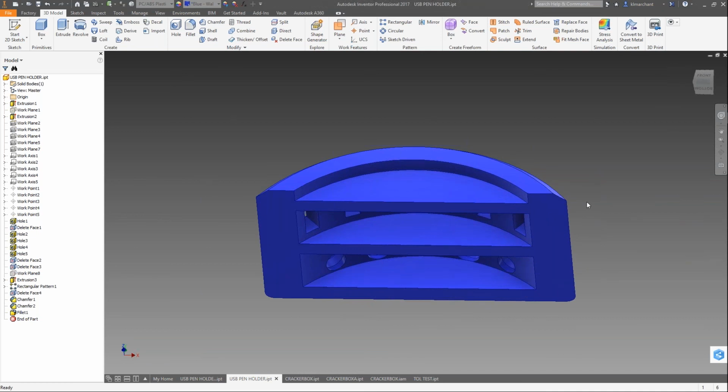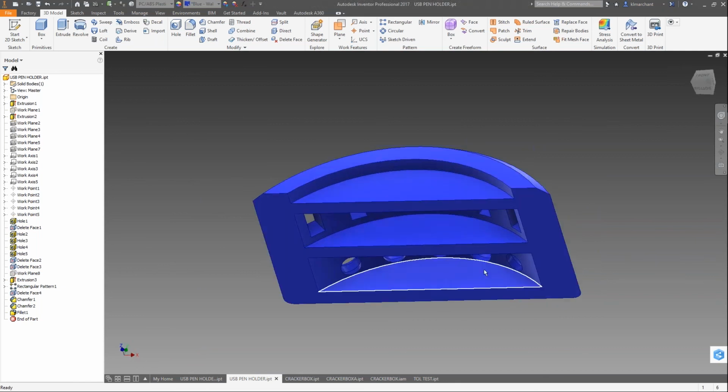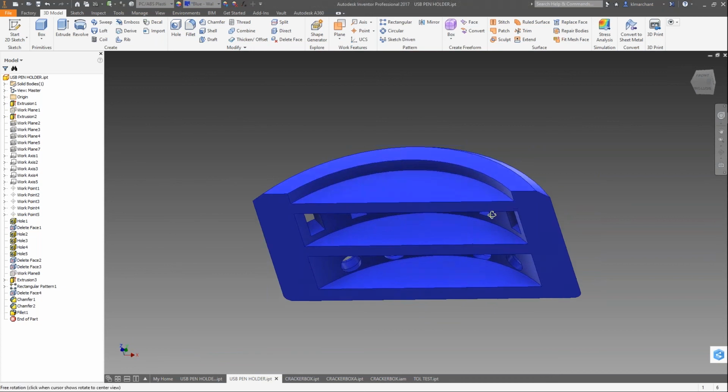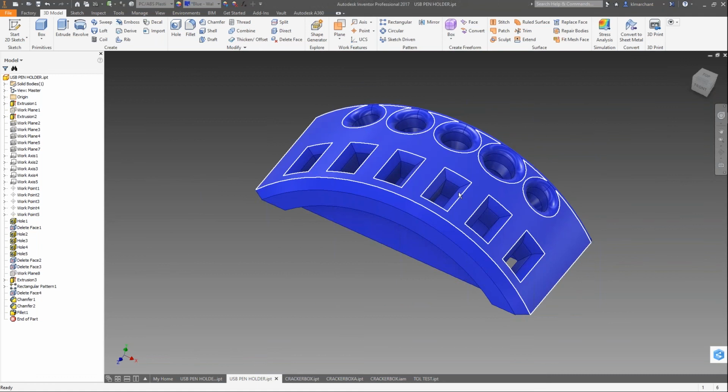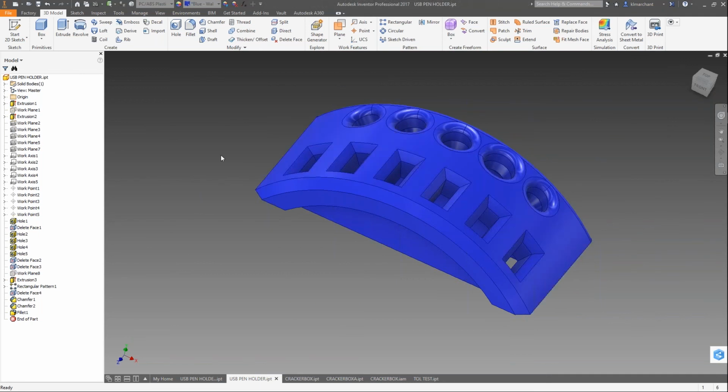That was beneficial because this printer's support material wasn't always the easiest to remove, and that's something we want to pay attention to with FDM or FFF technology. If we don't have dual heads and the ability to use rinse-away support material, we have to physically break it out of there.